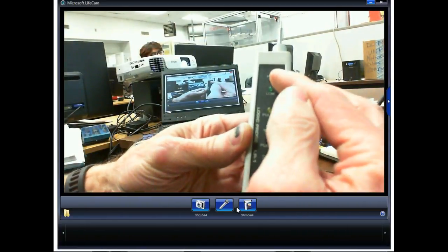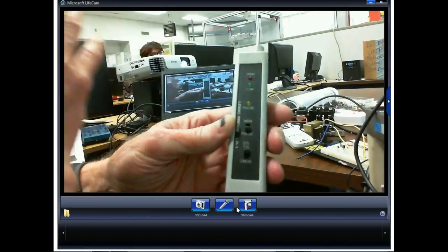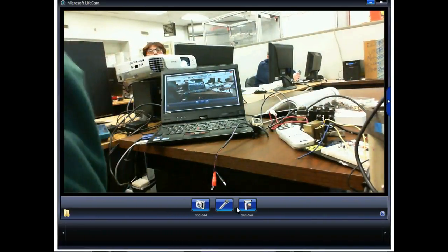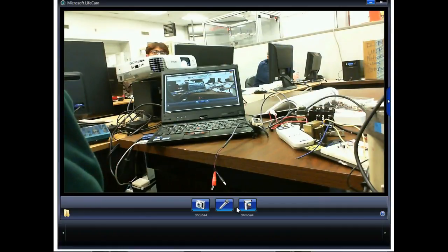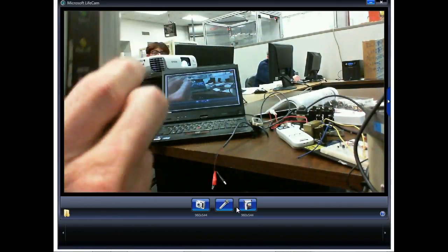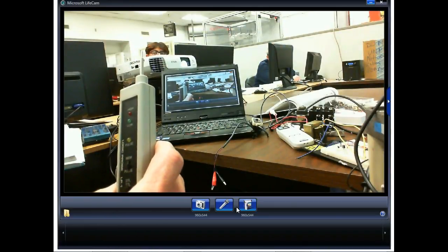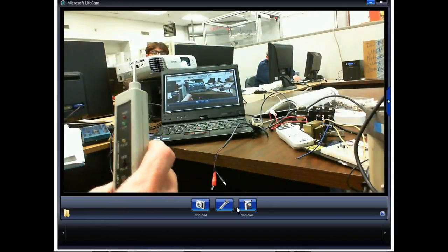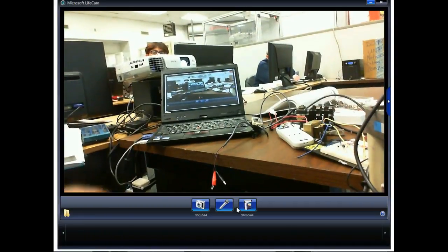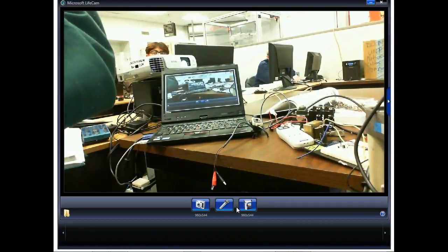If you're sitting here and this light flashes so fast that you can't see it, so we've got the probe in there and it gets a little pulse, the light turns on, but my eyes don't see it, then what happens is this pulse light goes to a circuit we call a one-shot, which means if it ever sees a change in state, the light will blink. You won't see the high light blink, and you won't see the low light. So if it's staying high all the time, and you see that pulse light blink, it means the low light turned on, but you didn't what? It was so fast you didn't see it.